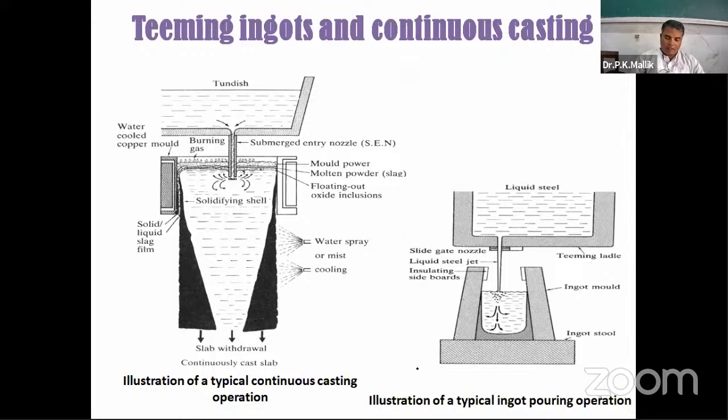The solidification of continuously cast slabs or ingots is also an obvious example of a heat transfer process. In this, the rate of metal solidification depends on the amount of heat extracted through the walls of a mold. For instance, by suitable adjustment of cooling rates in the upper section of the static molds by use of hot top compounds. Here you are generally using slag layers.